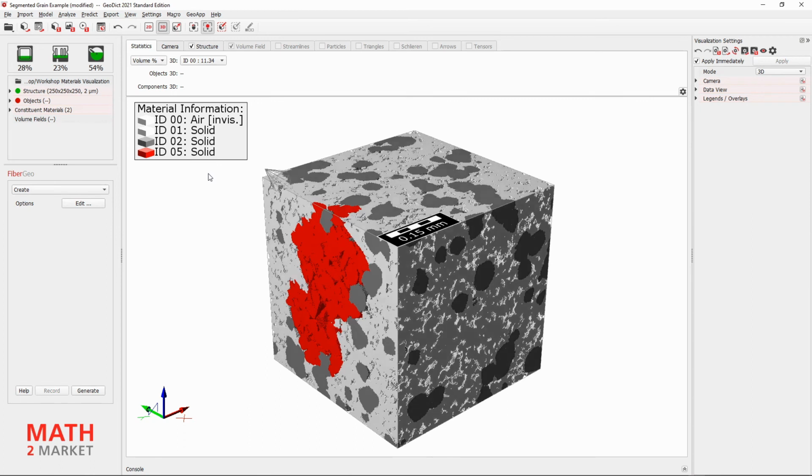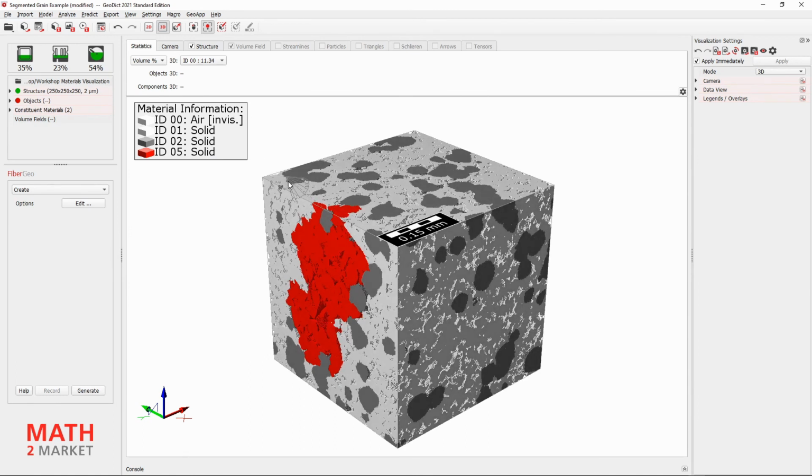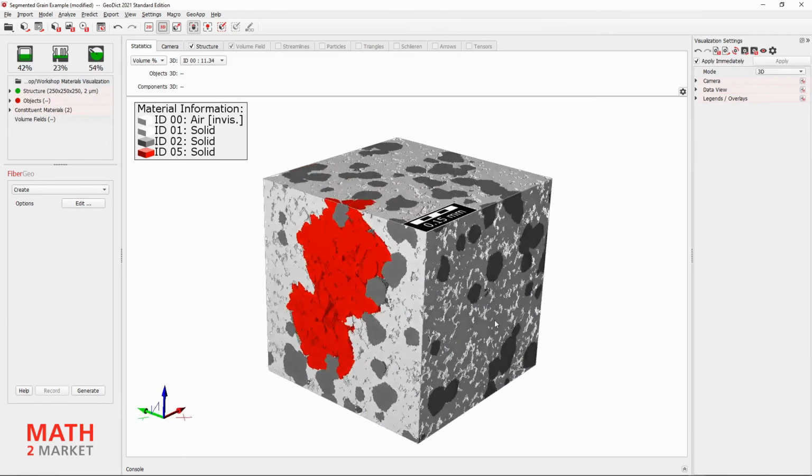We make sure that all sides are still clearly visible despite shadows, and that the shadow on this side here, the previously illuminated side, does not become too dark. So we adjust it like this, and as soon as we are satisfied with the result, we switch back to the mouse mode with the toolbar icon here. And now we again can adjust the camera with the mouse.